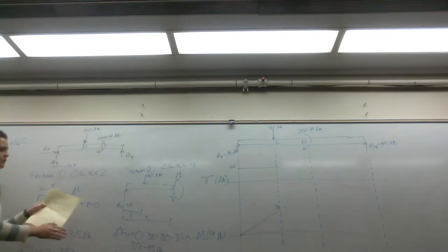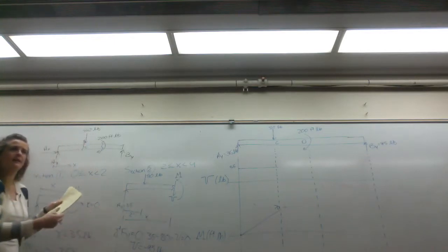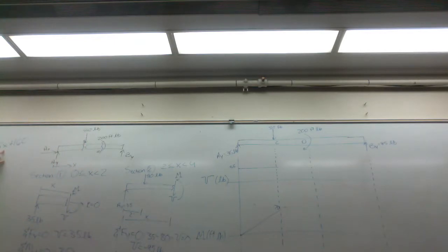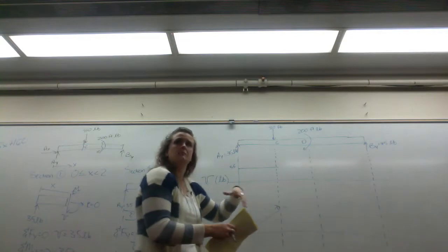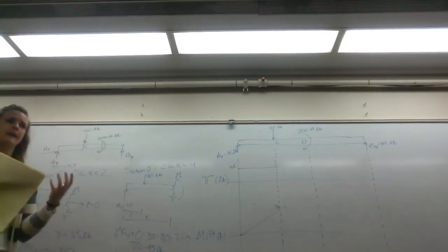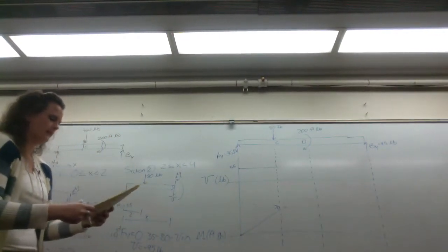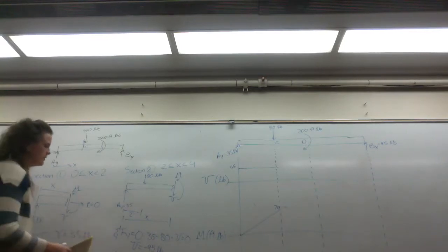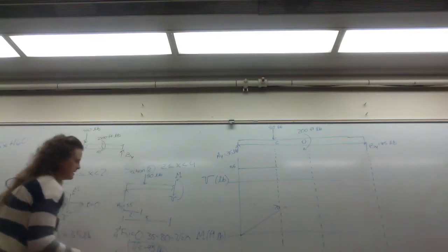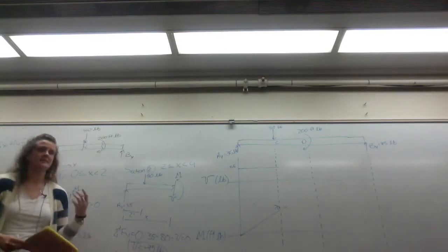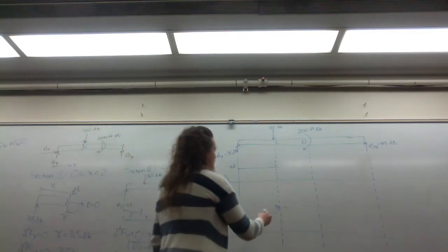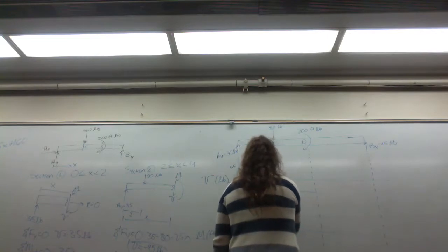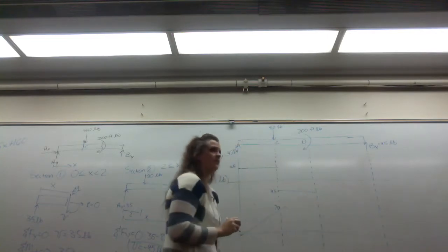Okay, so from A all the way up until this cut, our bending moment is again a function of x. So then we go over to our shear and bending moment diagrams, and represent your results graphically. So our shear force in the second section is negative 45 pounds. So we're at negative 45 pounds here.